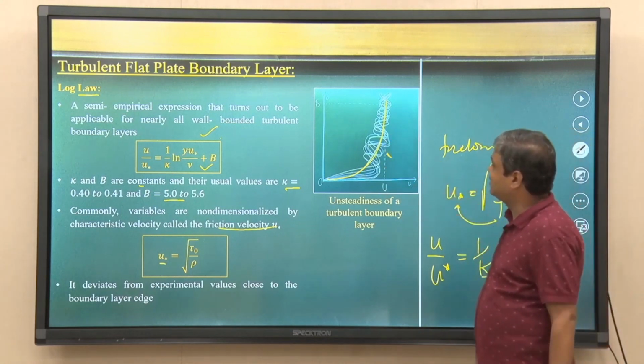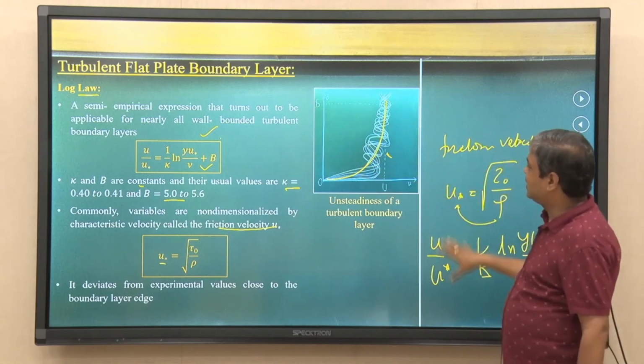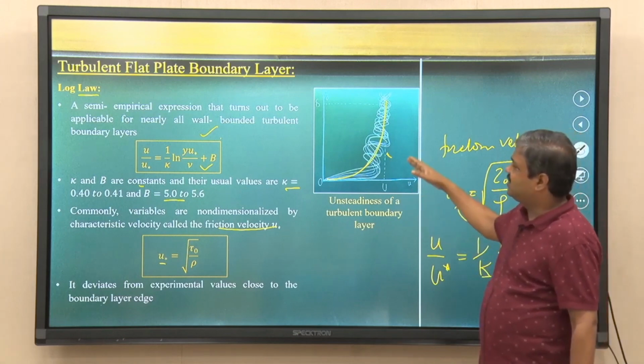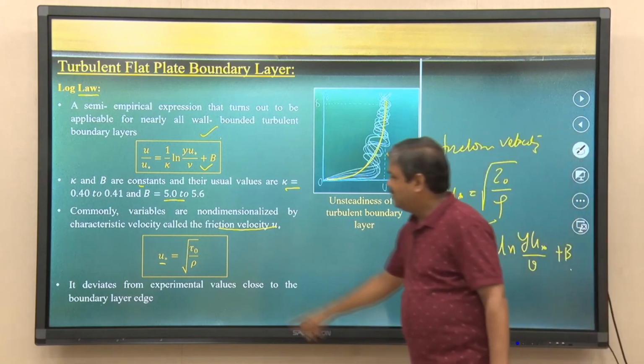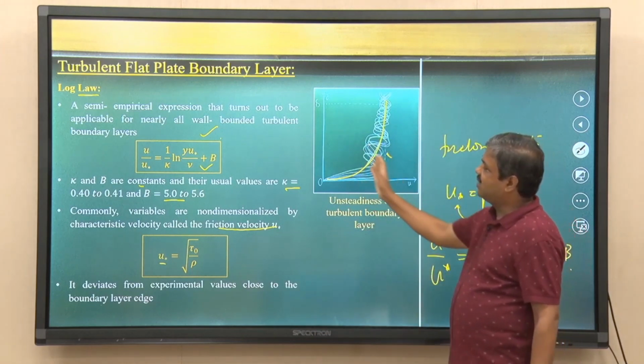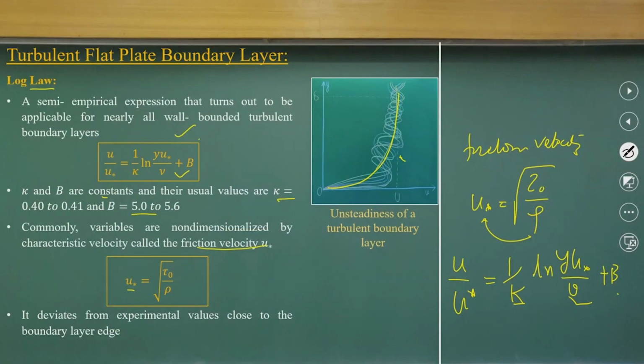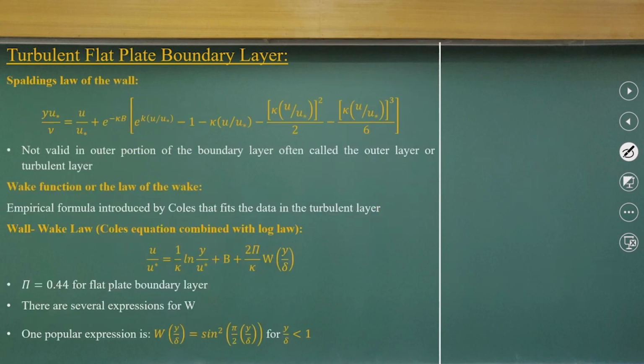This is the instantaneous velocity distribution. The time average velocities will come like this. So, we can establish the relationship between velocity distributions and tau naught, the bed shear stress, as a non-dimensional logarithmic function. The same has been tried by many. I am not going into details about Prandtl's and Von Karman's approaches; those are of interest for turbulent flows.